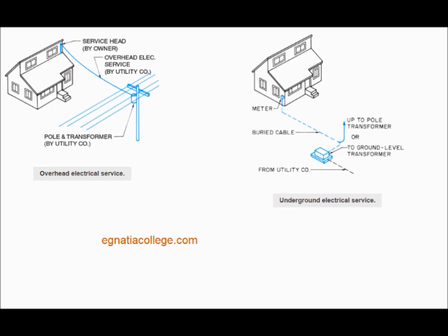Heavy commercial and industrial electrical services require multi-conductor feeders, and typically these are underground services from a utility transformer to a service entrance section in the designated electrical or utility room. Additional utility coordination will be required within the building. The placement of these underground electrical utility lines must be coordinated with the locations of other site and building utilities prior to starting installation.